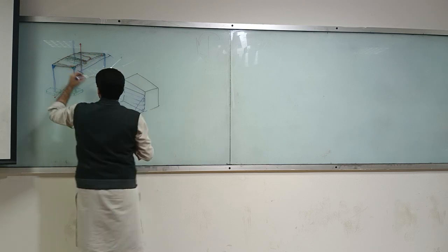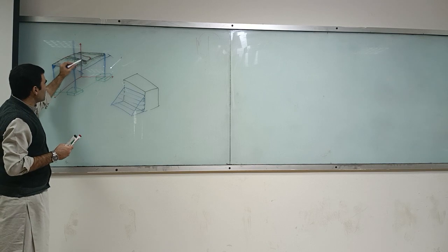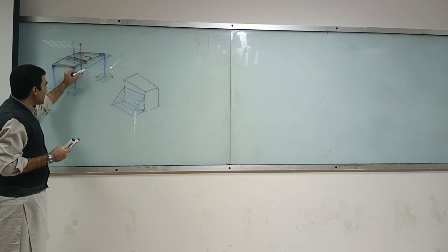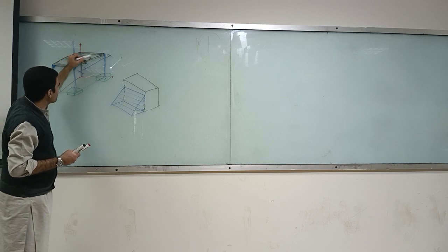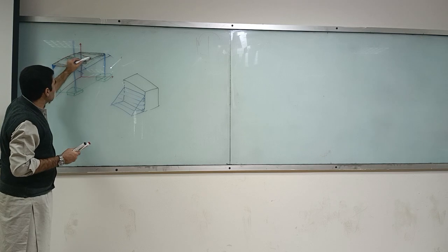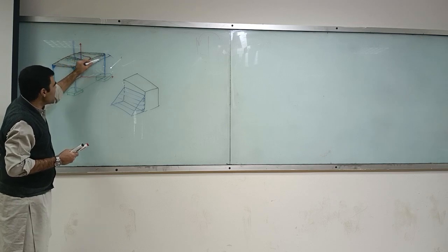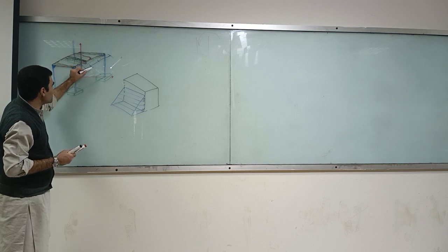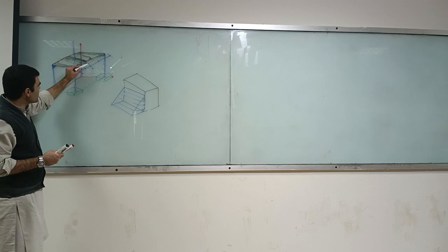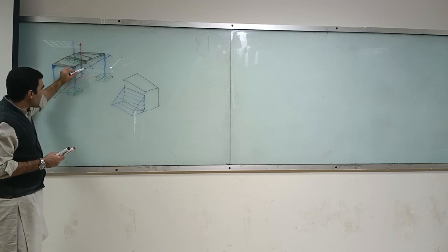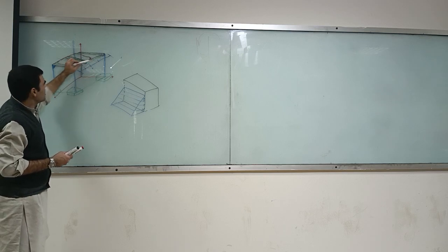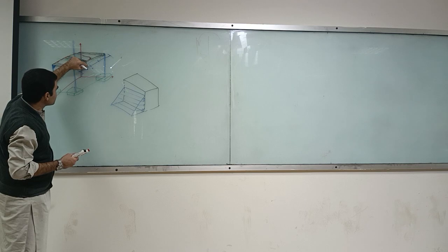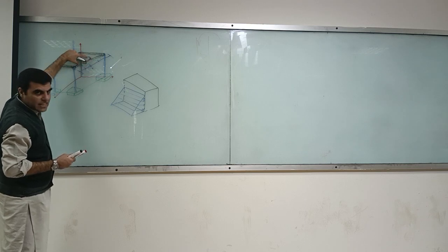If we have this length, what we would do is, between these two I'll take a half, and between this and this, I'll take a half of this length and half of this length, and this is actually the location of the beam. I'll put B over here. So this is the location of the beam. On this side the half length, on the other side the half length, and then for this beam the tributary area is this half and that half, so that is actually the tributary area.